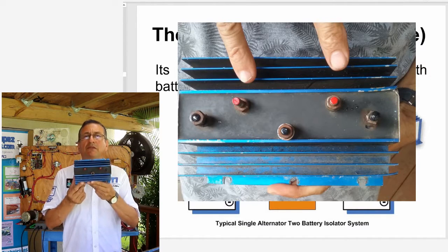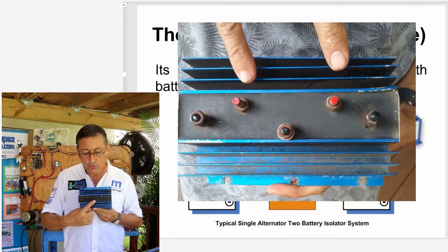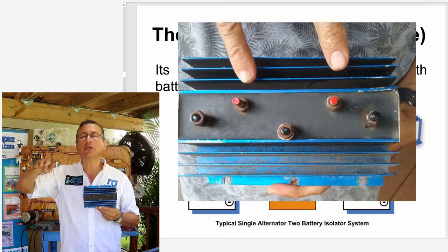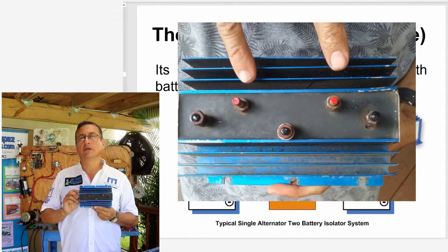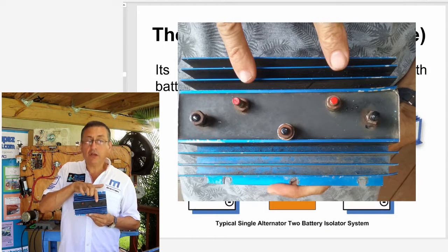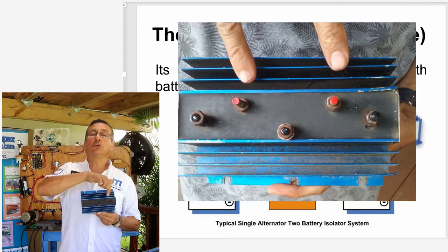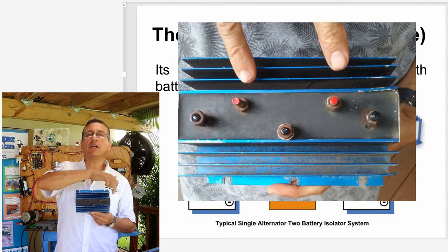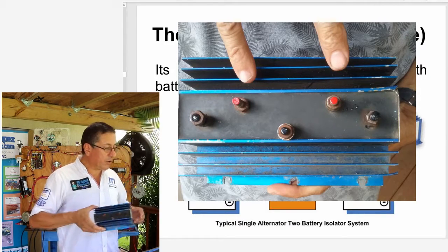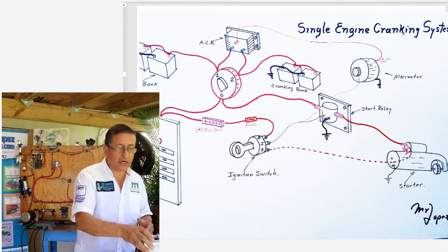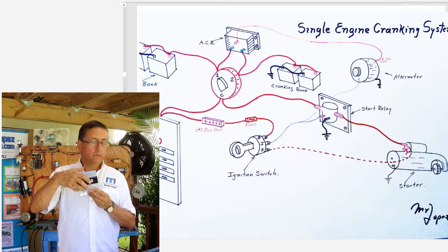This equipment, this ACR, has the ability to keep those 3 battery banks equally charged with the same level of charge, with power coming from, in this particular case, 2 alternators or 2 battery chargers or 1 battery charger and 1 alternator. What is the idea? For example, we are going to do the diagram right now to connect this one for 1 input and 2 outputs.